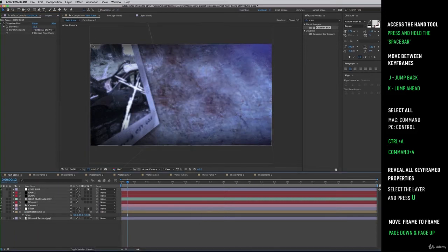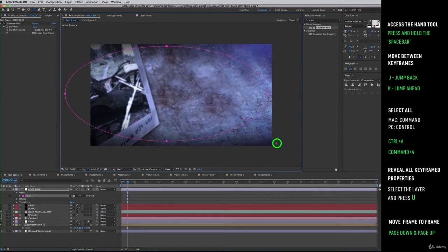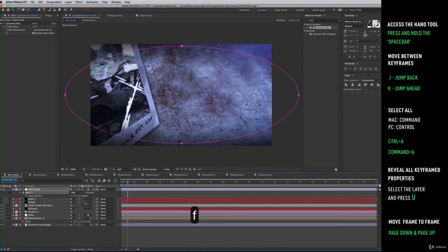With this line, the way you fix that is by selecting Repeat Edge Pixels, and that will remove this for us. With your Edge Blur selected, go to the Ellipse Mask tool, then select around our frame, something like that. Then invert the selection and feather it in a bit.